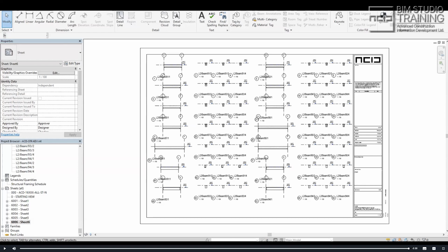So how do you do all the alignments? How do you do the design of the layout of the MEP? It's a lot of work, a lot of coordination work. And when we say BIM, we always come up with the notion of clash detection. You've heard about this term, right? Clash detection. For CCBC, this is one of your heaviest jobs. You do a lot of analysis, a lot of clash detection, and do the report, right? How do we do this clash detection?